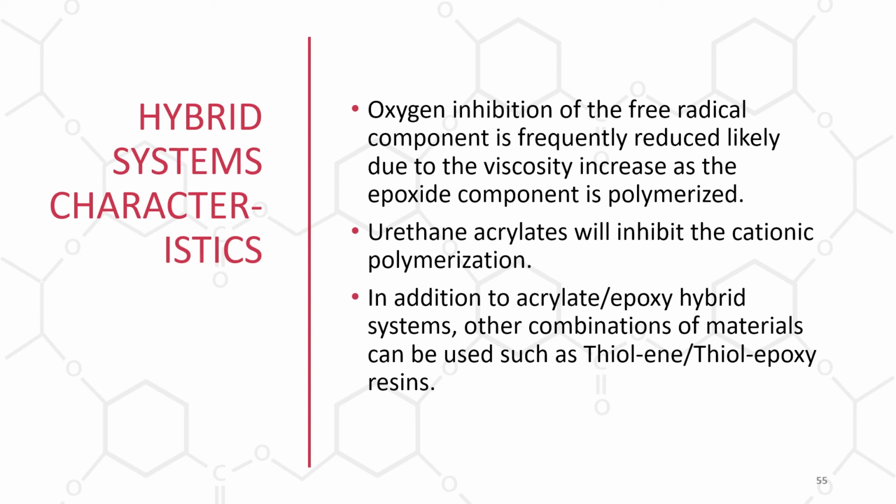In addition to acrylate epoxy hybrid systems, other combinations of materials can be used, such as thiol-ene and thiol epoxide resins. However, the bulk of hybrid systems, and we're talking about UV curing, tend to be acrylate and cationic systems.